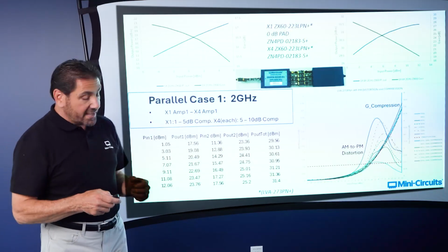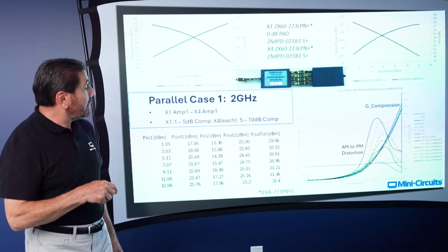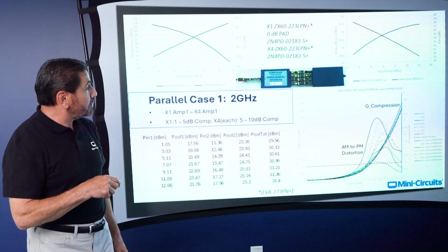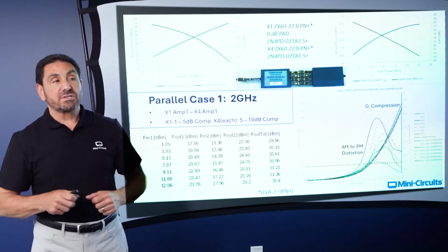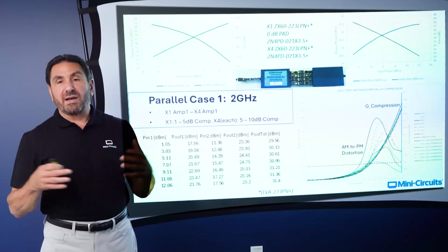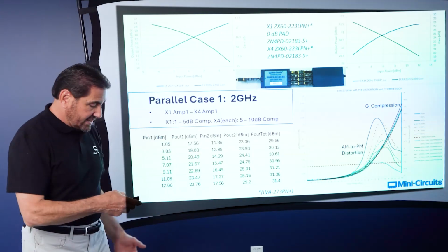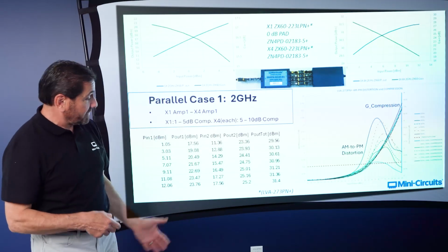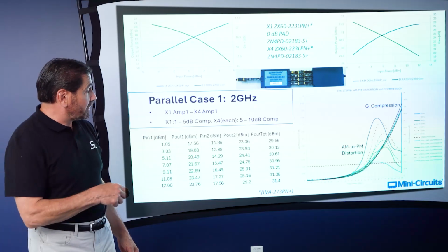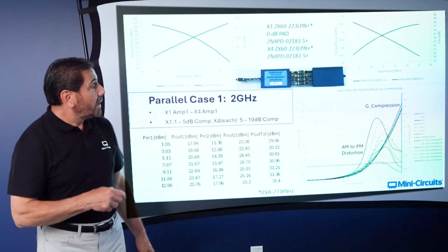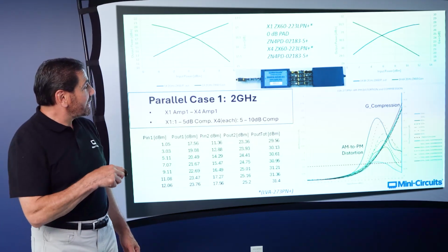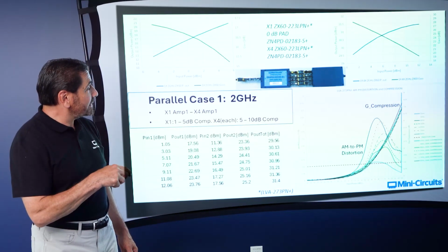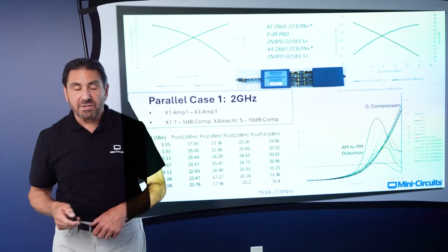So we're going to start out with now a little bit different. You see here the single stage. Here we have a 0 dB pad driving the 4. So it's literally one stage driving 4 stages without any real thought to optimizing power levels. We're just going to go for, say in this case, maximum output power. So actually, if you're looking for a 1 watt amplifier, 2 gigahertz, this is not a bad combination. We use our reference LVA 273PN. It's just in a ZX60 connectorized configuration here.